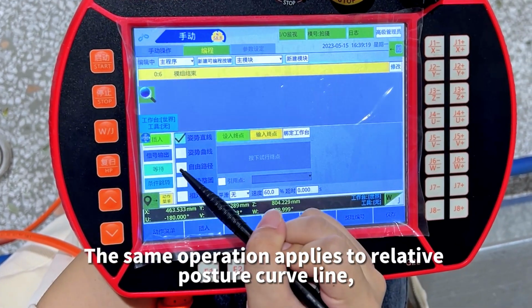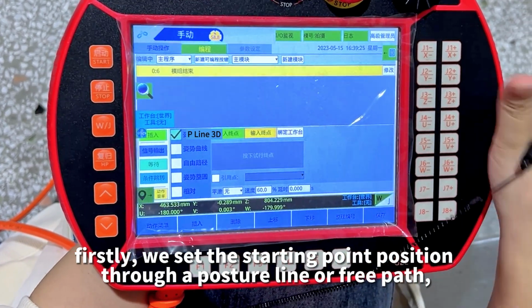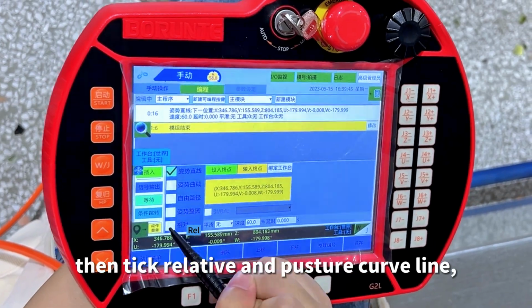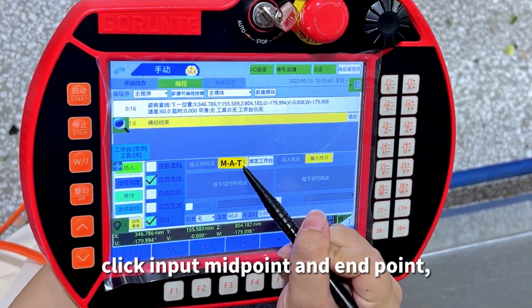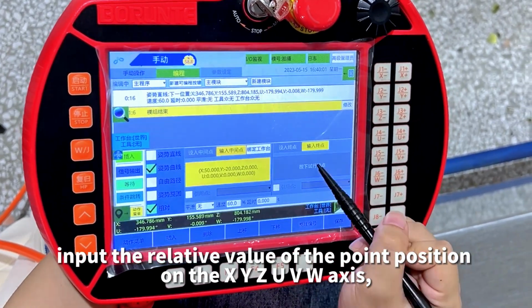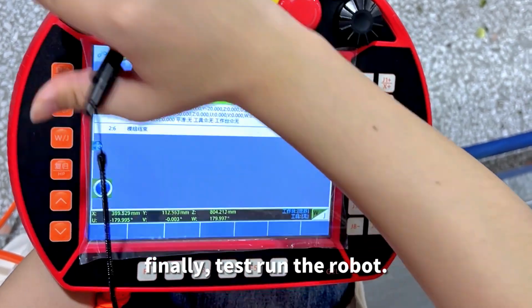The same operation applies to relative posture curve line. Firstly, we set the starting point position through a posture line or free path. Then tick relative and posture curve line. Click input midpoint and endpoint. Input the relative value of the point position on the XYZ-UVW axis. Finally, test run the robot.